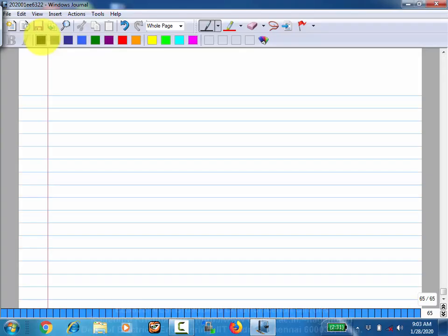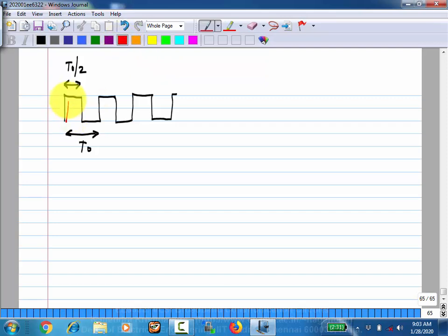So we were discussing the spectrum of a jittery clock, where we have the ideal clock, 50% duty cycle and a period of T naught, and a real clock whose edges are displaced from the ideal ones by some amounts, which I will denote as a discrete time signal.